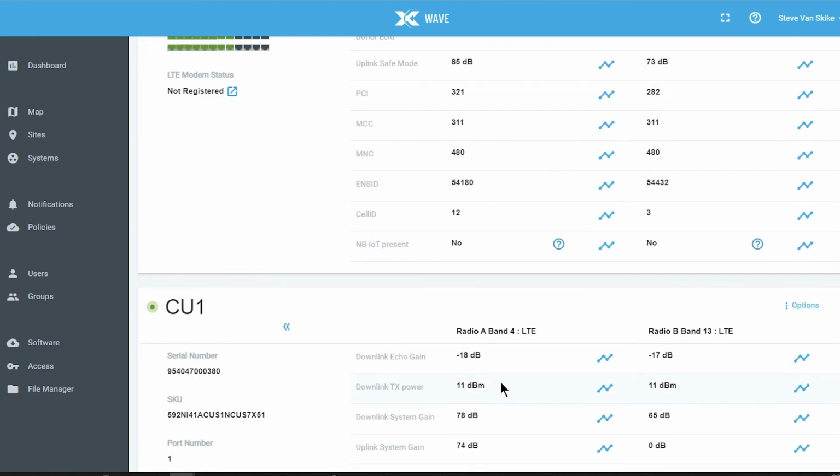Because I would go down and chart the downlink power. It should be hovering somewhere between 10 and 16 dBm, depending on the channel bandwidth, and it's going to go up and down with loading. But if it's low, if it's really peaking at 0 dBm or minus 10, then I have a 10 to 20 dB issue to contend with.